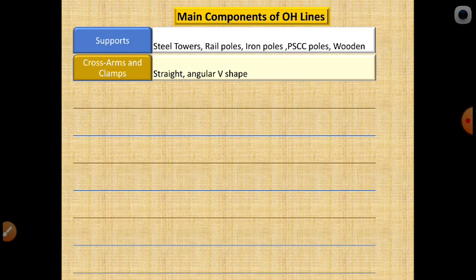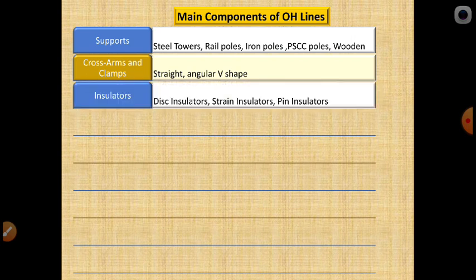Next, another part on which we are going to place the insulators. So what is the insulator? Insulators are of different types. Already we have seen disc insulators, pin insulators, strain insulators. In case of strain insulators, LT shackle insulators, and in case of HT we can use the same disc insulators as strain insulators. What is the purpose of an insulator? These are used for supporting the conductors and also taking the strain of suspended conductors. Generally, these are the functions of insulators.